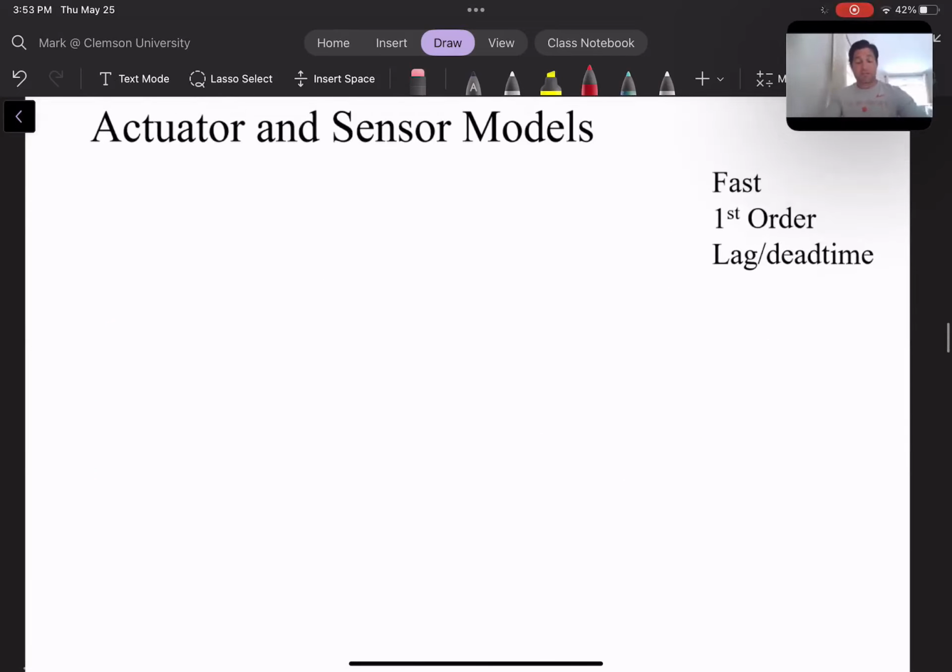All right, so let's go through. There are really two types of models that we can use for an actuator. Generally, a control valve can respond first order. And as we saw, the model for a first order actuator is dF/dt equals 1 over the time constant, times (F specified minus F). What this means is if F specified is greater than F, this overall term is positive and the flow rate should increase. That's what we would expect.